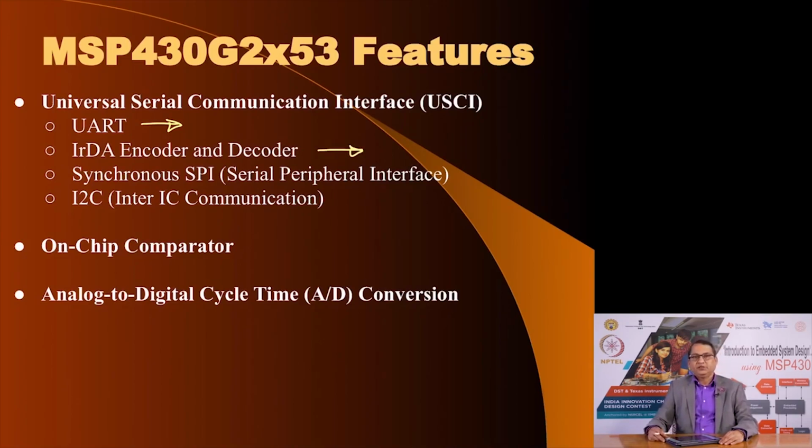It could be used for serial peripheral interface, what is called the SPI bus, and if you remember from those discussions, SPI and I2C, that is inter IC communication, were classified as intra device communication, that is within the gadget, that embedded system that you are building. If you want the microcontroller to communicate with an external IC which has this or this protocol, you could use the built-in communication capability of MSP430 to communicate with devices within the system.